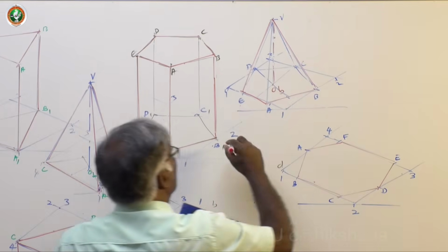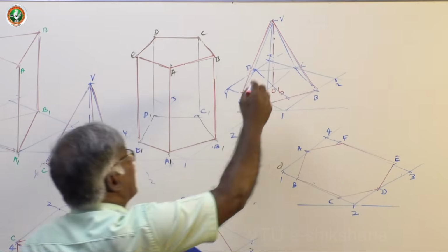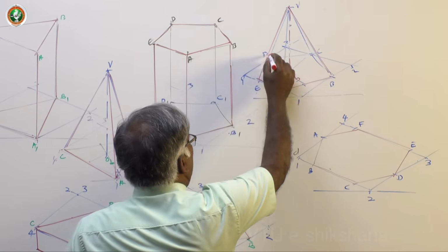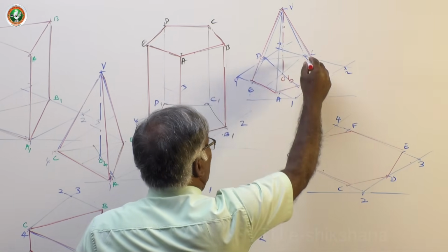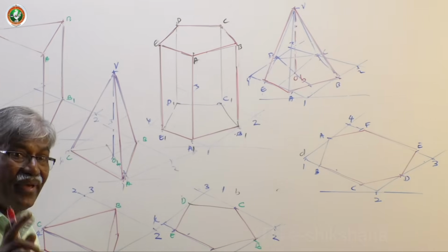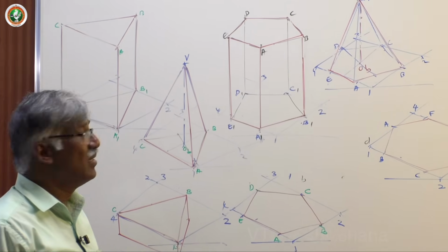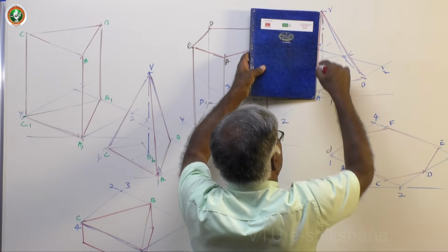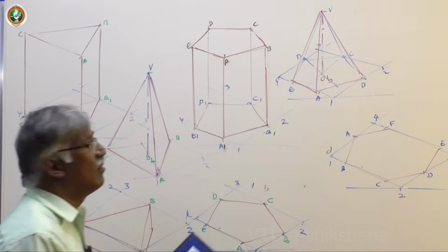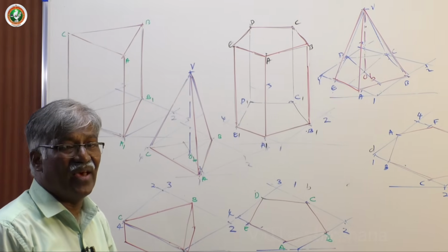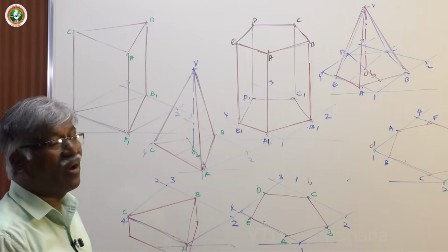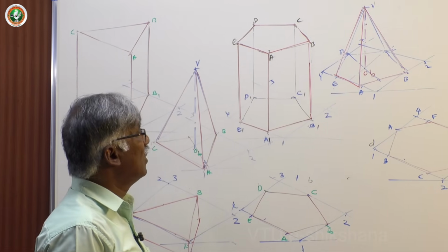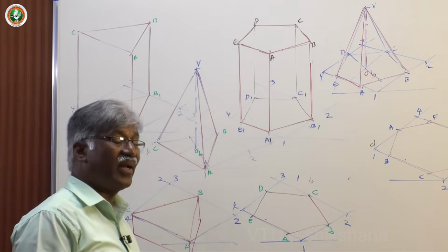This also visible. Okay. Now, what about VA? VA is visible because this DE, DC, CB are not visible because that is base edges other than boundary lines. Next, VA is visible because it is crossing the invisible surface. That's all. All remaining lines leave as edge. If it is solid, then you would have marked dotted line. So otherwise, this is the solution for isometric projection or view of a pentagonal pyramid.